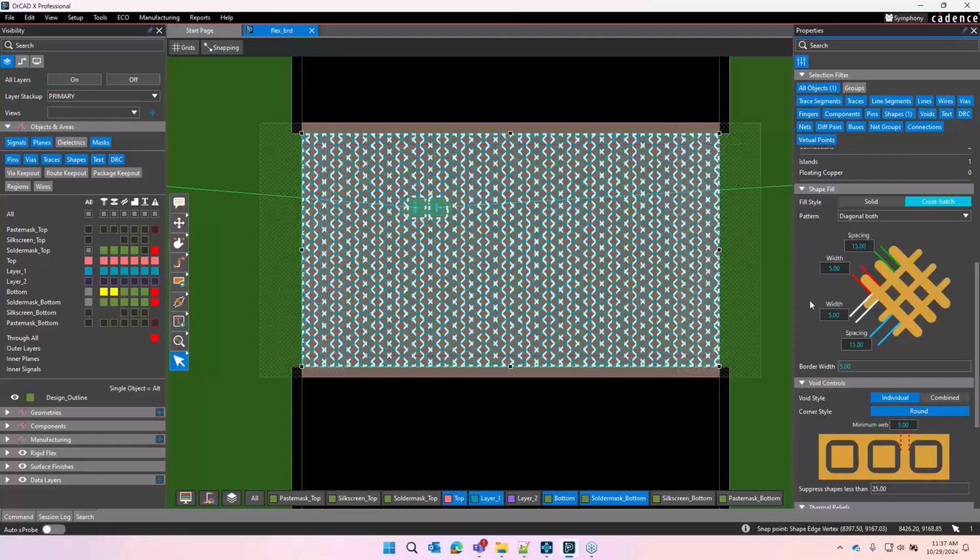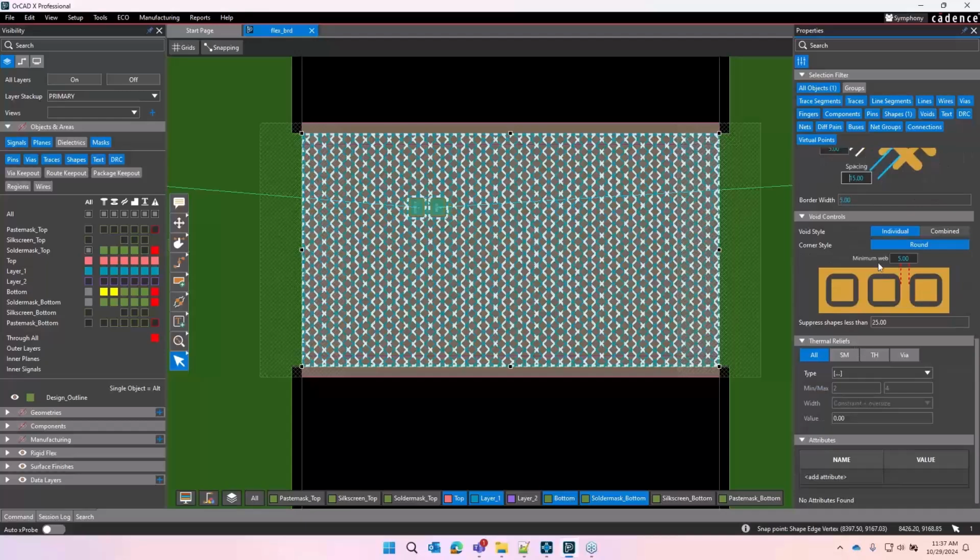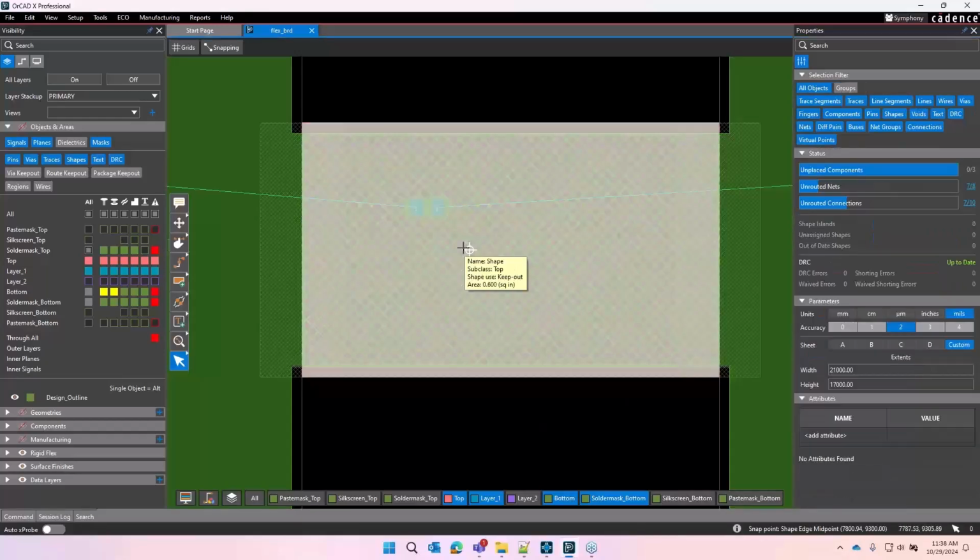Not quite as ideal because your return path might line up on top of a return line or off of one, which is going to change your impedance pretty radically. You can change the spacing here. These fields are dynamic. You can change them right here. And there's a few more choices for reliefs and stuff like that that you can choose here. Okay, so that's my crosshatch shape.